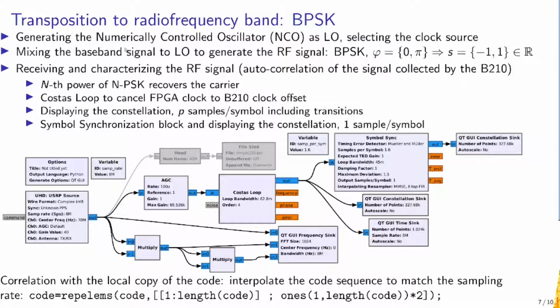So we're going to start with the most simple modulation scheme that can be implemented in the digital world, and that is binary phase shift keying. Again, that's the same modulation scheme as used on GPS, developed in the 60s and 70s, so you can see that that was a convenient way of doing things, and yet it's a very efficient way of modulating, because by acting on the phase, we have the most efficient modulation scheme.